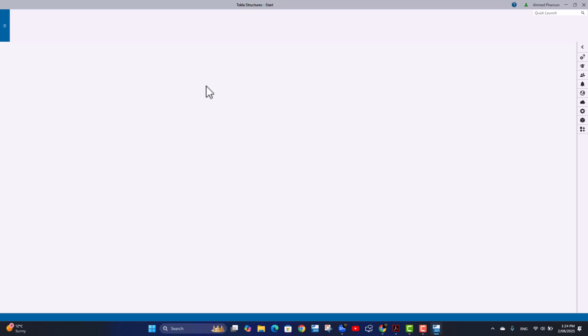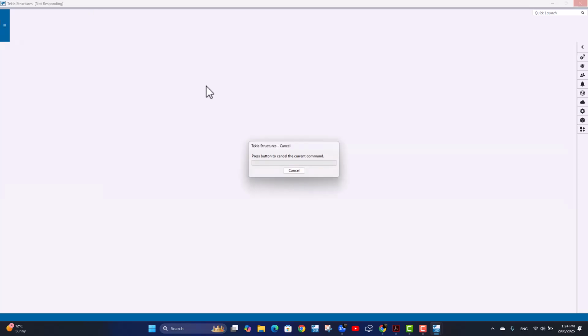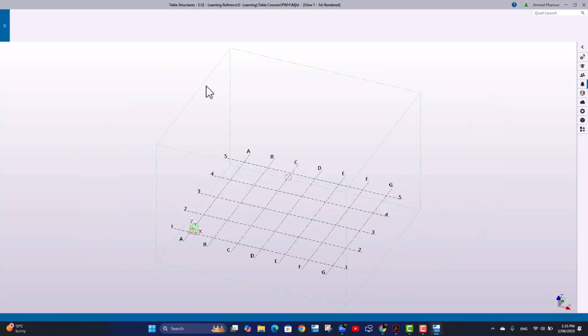When the model is created, it's not like an AutoCAD file, a single file. No, it creates a big folder that contains many subfolders and many files, including group files that are used, materials that are used, attributes, and the building geometry and shapes. So in Tekla, the project is not a single file as in AutoCAD. It should be opened through the program and it contains a lot of files. They are all forming the library of the same project, but they are not a single file as in AutoCAD or in Excel or in Word or any other program.